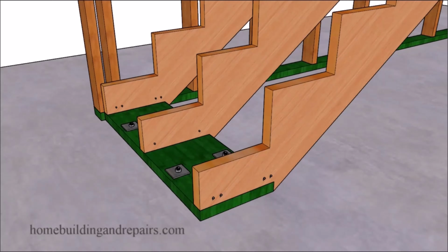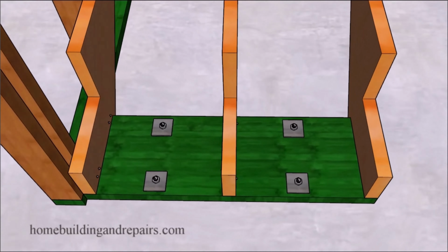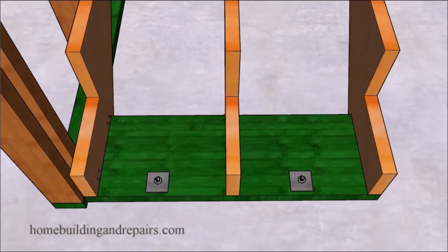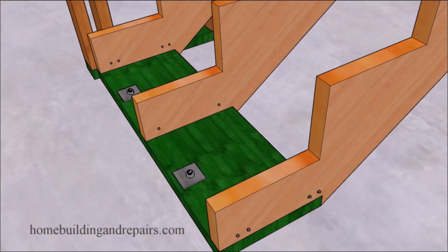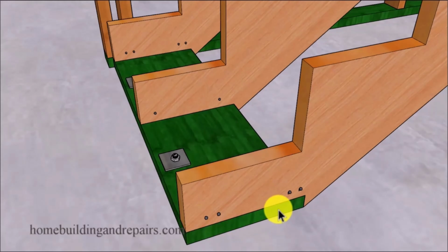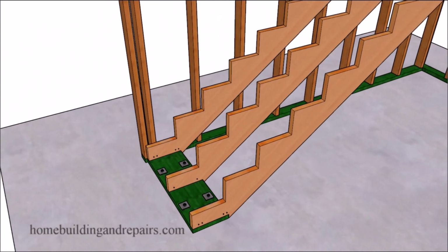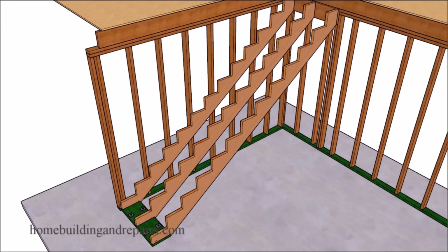And if you don't like that idea, what about this one here? Grab a huge piece of lumber and securely anchor it to the foundation. Don't just secure it in the front or in the back. Otherwise, you could end up with the board twisting and forcing one side of the stringer up. And that's probably not going to happen if you have enough base framing anchors to prevent that from happening.